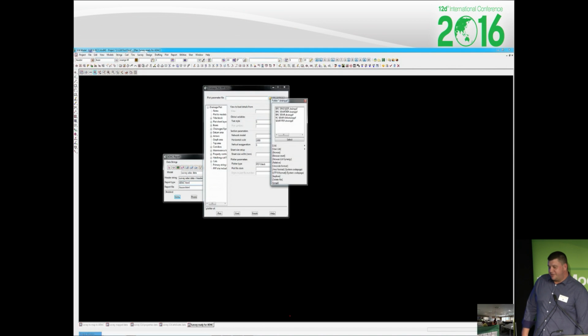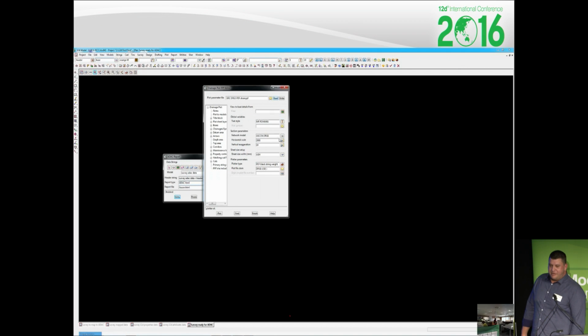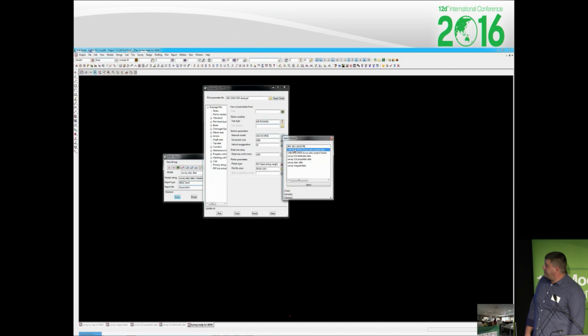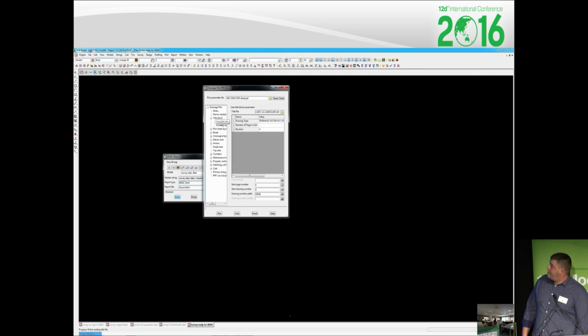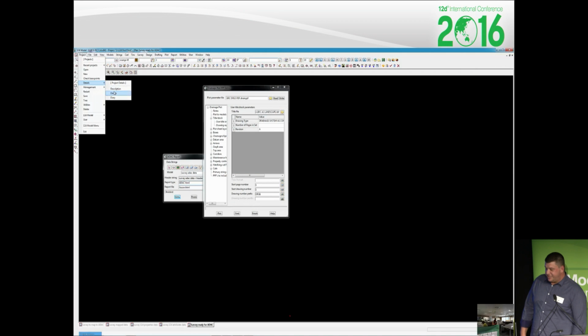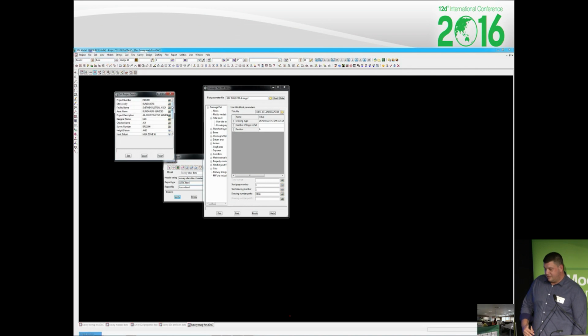And now we've had old school engineers say, I don't like that, I want to see paper plans, show me some paper plans. So we use our plot frames, our PPF to generate long sections of the whole drainage network in shoulders. This makes use of the project details you fill in at the start of the project. And that contains the survey information as well, so your datums, reference marks, scale factors.